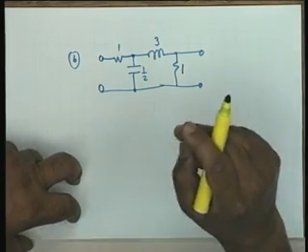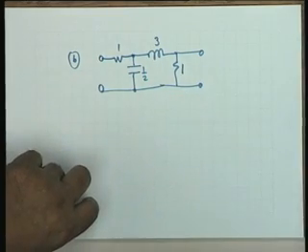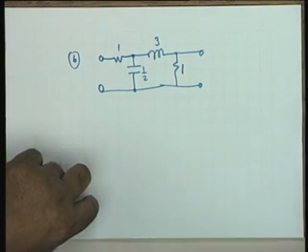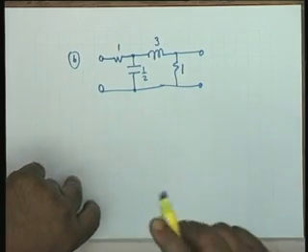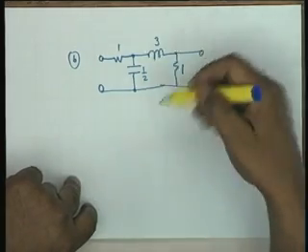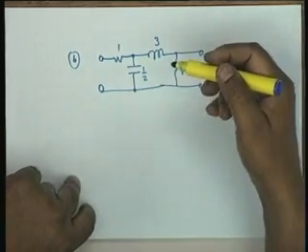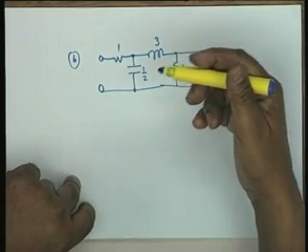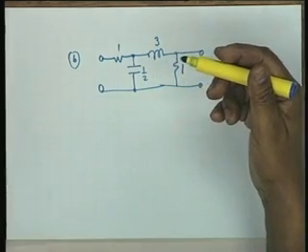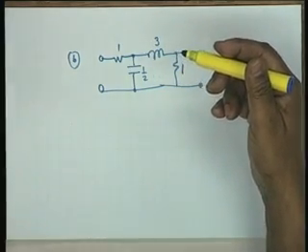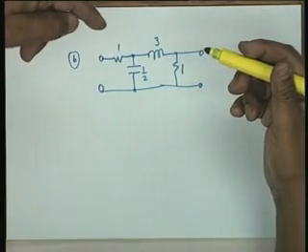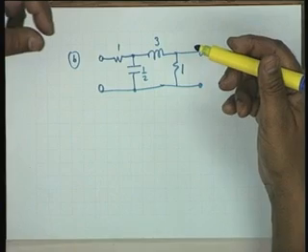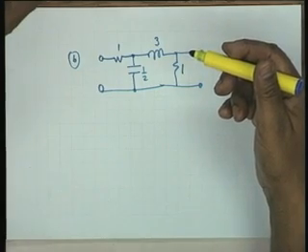Residue condition validity, as I said, happens only in 2 element kind networks. It is not necessarily valid in 3 element kind network. This is an RLC network, but still the question says show that the residue condition is valid. Therefore, you shall have to find the poles of the parameters, the residues there, and show that the residue condition is valid. Is the point clear?